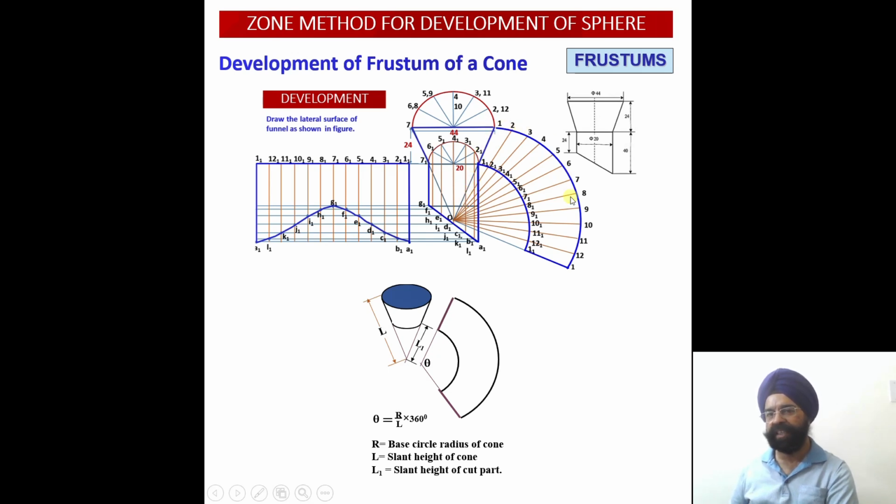So this will give us the outermost portion of the arc. Then we know the segments. So this segment length or width we are going to mark, and then 12 segments we are going to draw over here. Then corresponding to the removed portion, we are going to mark another arc, and then the interior segments will correspond to the smaller diameter circle over there.